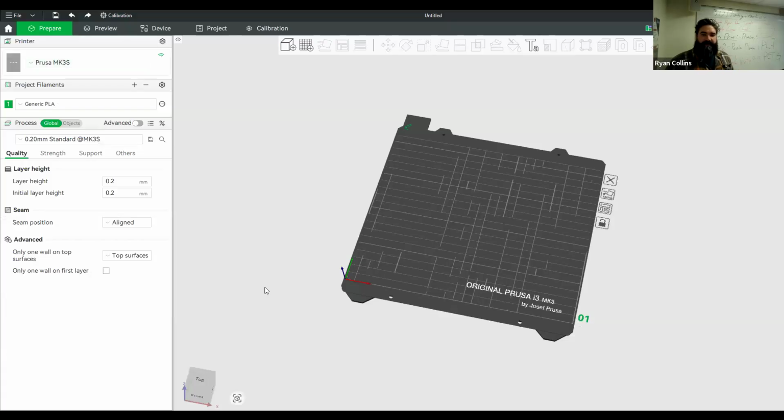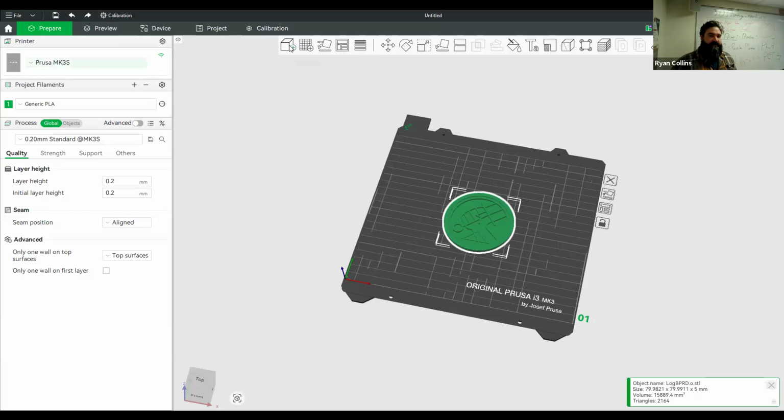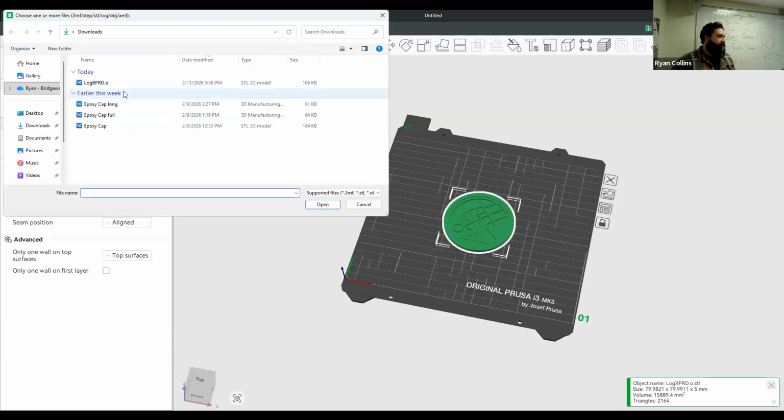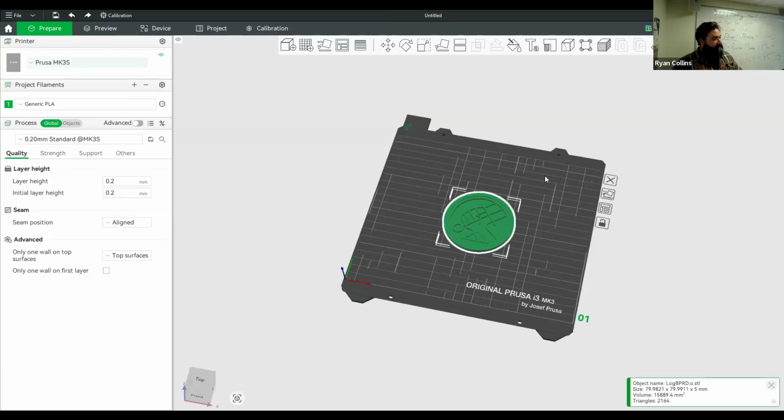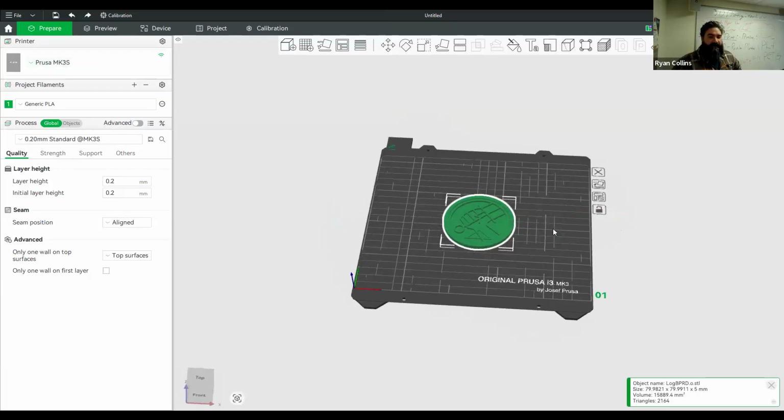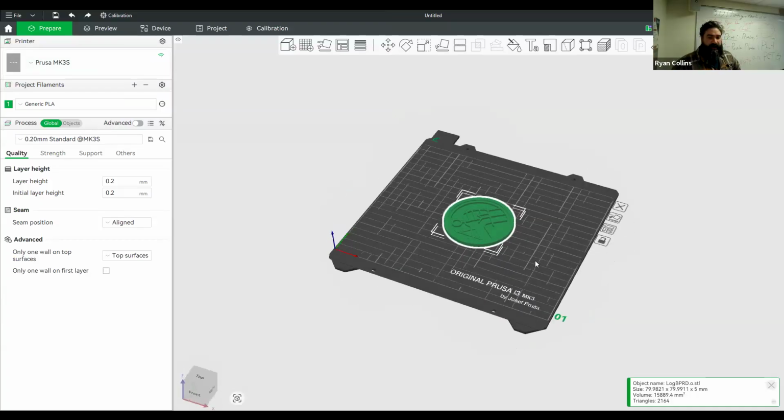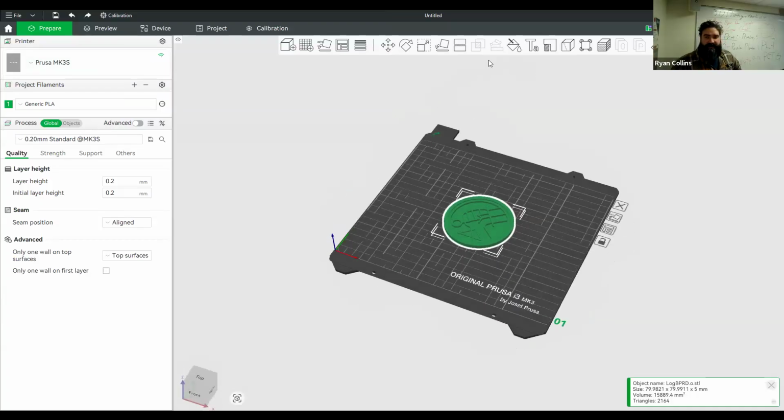And all I have to do is take the STL file and drag and drop it. You can, of course, also bring it in if you're in the program itself. In the top here, this little square with a plus, same deal. So drag and drop or bring it in as you want. And because this is just a direct print file, should be good to go. If yours did not come in flat like this, you need it to be flat on the project space. Let me rotate this so you can just see what it might look like if it didn't.